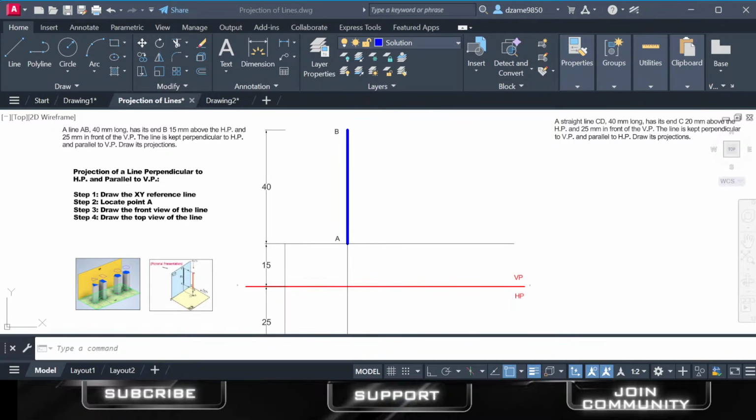Let me take you back for a moment to manual drawing class. When we are on a drawing paper, you don't use just one pencil, correct? You usually have different pencils: 2H, 3H, 4H, HB, and also H, among many others, or sometimes B. And you know very well these pencils are used for different purposes: HB for dark outlines, H for light lines, and sometimes 2H for very light construction lines, but 4H is the best for that. And sometimes you also use stencils for circles, symbols, or standard shapes. Now, something very important I want you to understand here, okay?